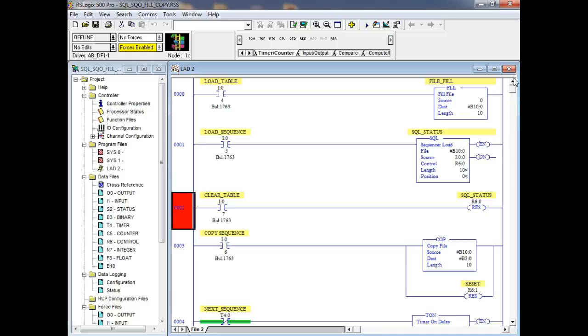If I get time, I'll write something to show you how we could actually input analog information into a program, which is pretty neat. So what I want to do is strip off the bits that I'm using to control the sequence, right? You understand that? I'm using the input bits 4, 5, 6, and 7 to actually control the program, and then I'm using inputs 0, 1, 2, and 3 to set up the sequence. You understand that? Yes or no?